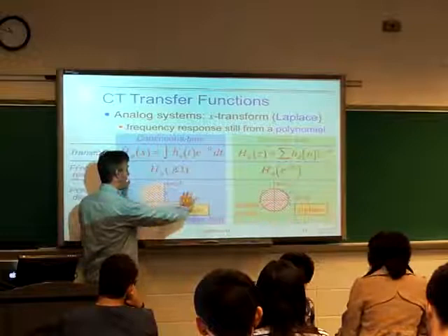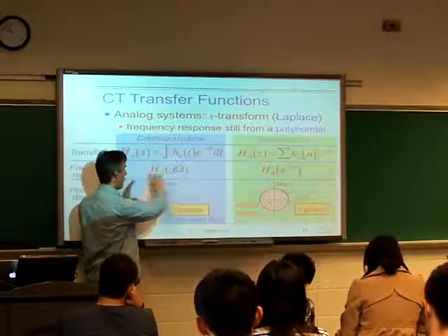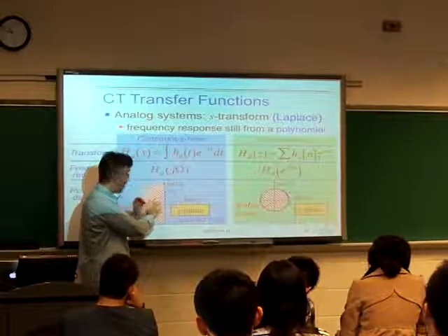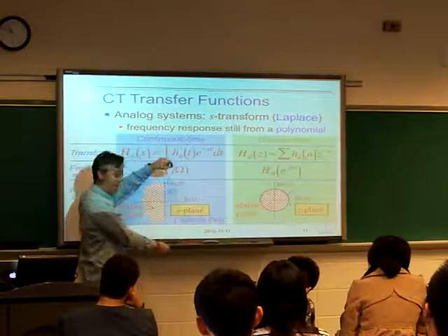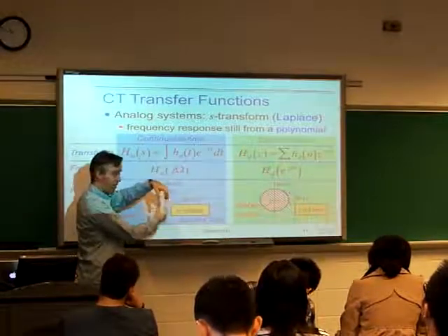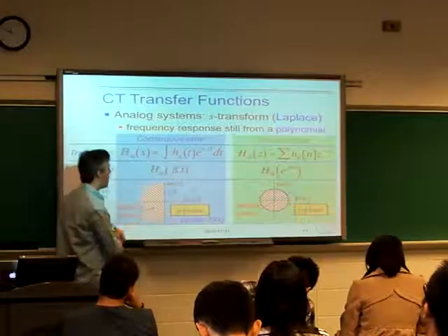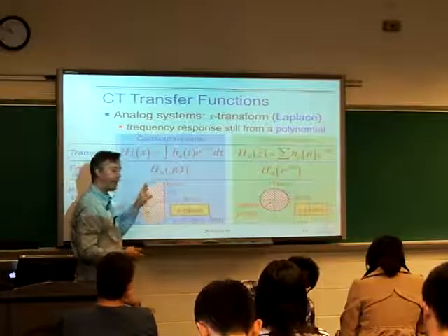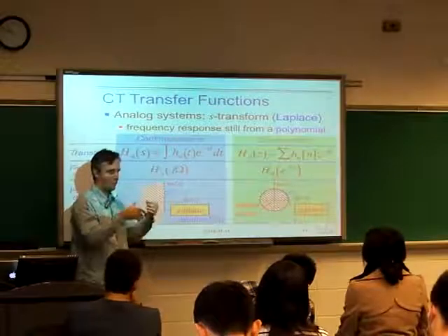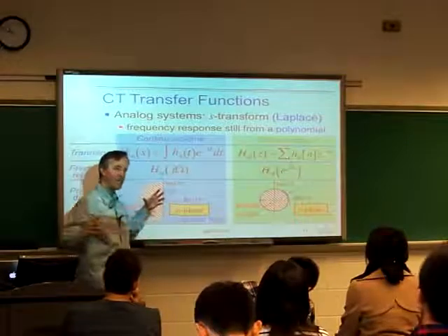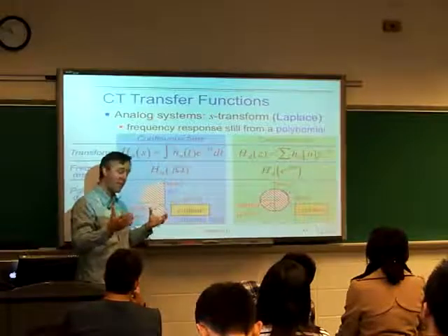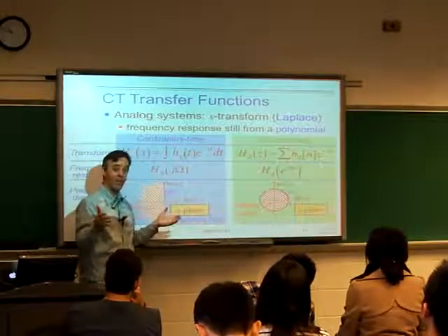But scaling now is interesting because if I scale it, so if I have not h of s but h of alpha s, the left-hand half plane remains left-hand half plane. The imaginary axis remains the imaginary axis. But now all that's happened is that the frequency values on the imaginary axis have shifted to new frequencies. And so the nice thing about Laplace domain systems is if you just substitute in alpha s, then you still end up with a filter, a system whose frequency response you know. All that's happened is the frequency axis has been scaled by the factor alpha.